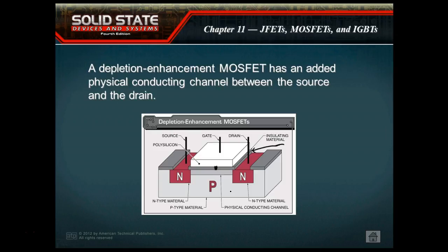So we take extra precautions, and like I said, y'all remind me when we come back on Monday, because that's a pretty good way off, to show y'all some of our static wristbands, our static mats, some static bags and some static foams that we would use when we start playing around with these MOSFETs. Now JFETs, we don't have the problem, because it does not have that real thin layer.